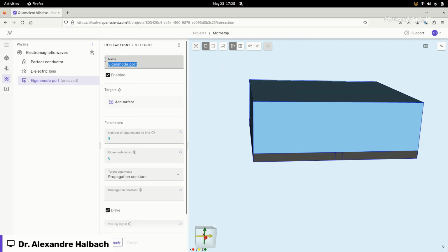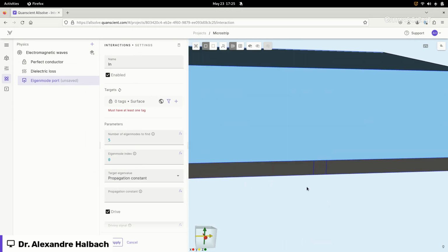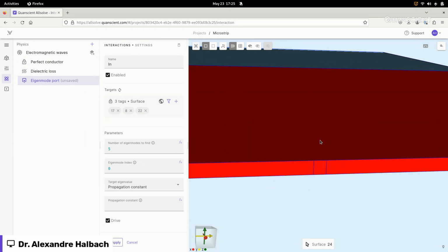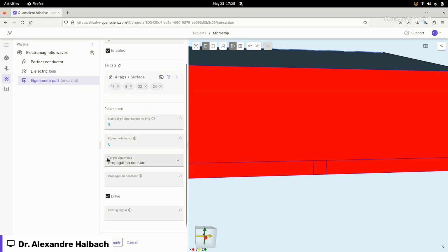So we will have the input eigenmode port defined on the surface. You can also draw a little surface around here. Here, it will be very accurate by just capturing the entire surface. And then you can tune it the way you want. But typically here, you just have one single QTEM mode that can propagate, so there's not much tuning needed. You can provide a target dielectric permittivity. And since there is only one mode, there's not much else to do.